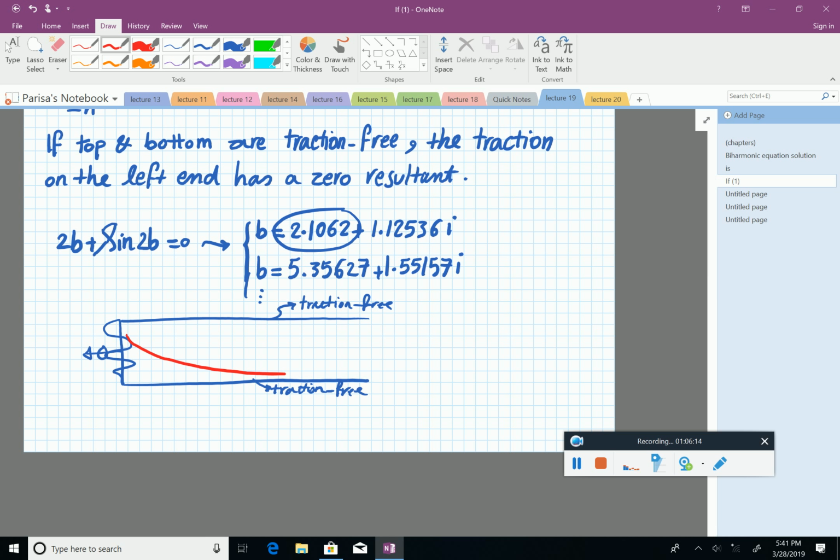Okay, why do I care about that? This problem, the resultant is 0. Can I sum it up with some other problem? Like imagine another beam, you have some moment on the left hand side, I can superimpose this problem over some other problem. The resultant is 0. You don't even know that you did that. Do I make sense?